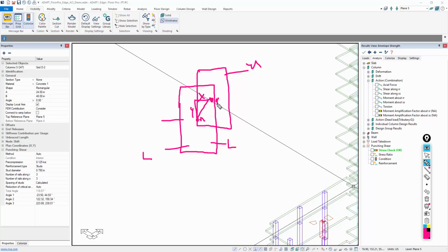So this is considered a planted column in this case, and this is exaggerated. But if you have some column, let's say this is brought in from Revit or maybe a conversion from a CAD file, and there's a tiny gap between the two centroids, then there is some tolerance that we look at, and the program would treat this similar as if they're stacked concentrically.